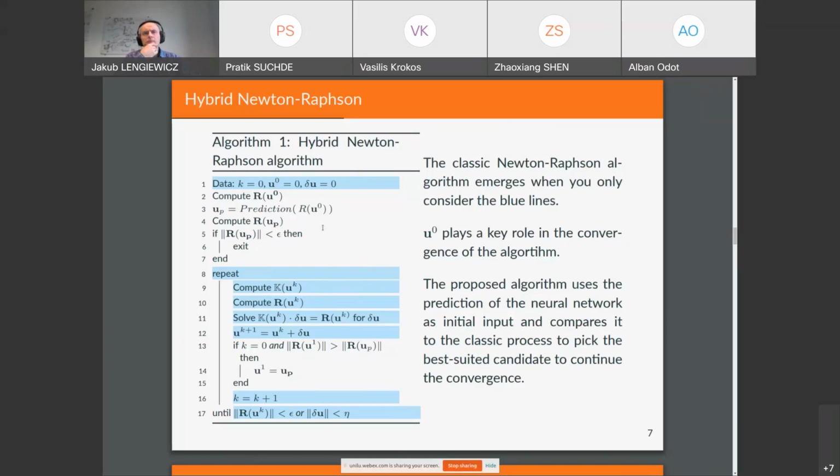And we modified the solver in order to have a first computation of the residual forces. So the residual forces are external forces minus internal forces. And since we are at the rest shape in the beginning, the first one is only external forces. We predict a first displacement using the neural network from those external forces. And this gives us the first approximation of the final displacement.